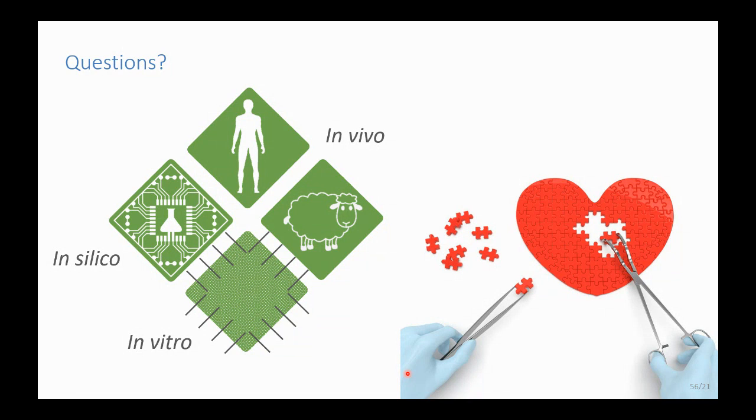Yes, and I think especially the fluid structure interaction model shows that, and that will indeed become more important as soon as we include that, because at this point we just included a uniform pressure, not even a varying pressure, but just a time averaged pressure. So that hasn't come into play yet, and you're absolutely right that we need to include that, and that dependency will indeed induce more inhomogeneity.